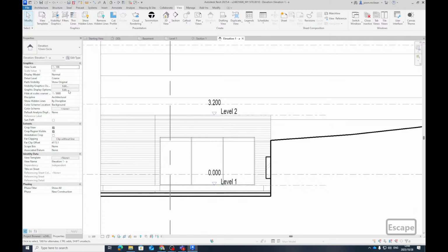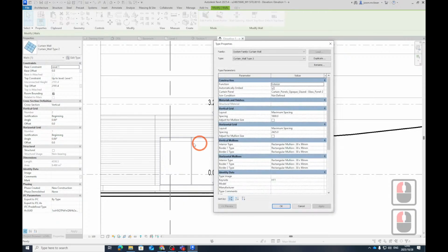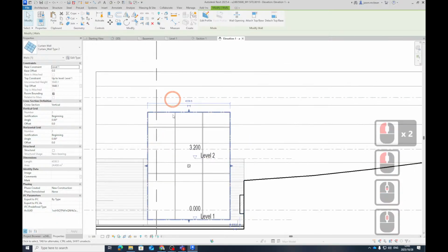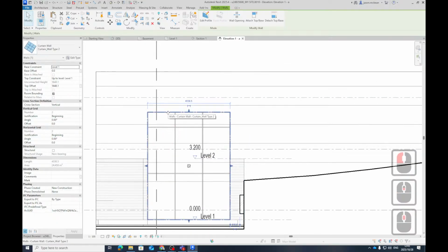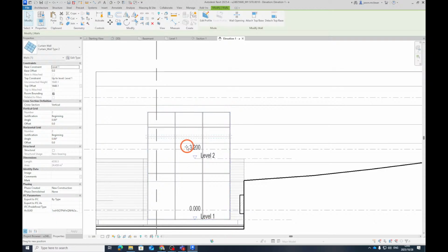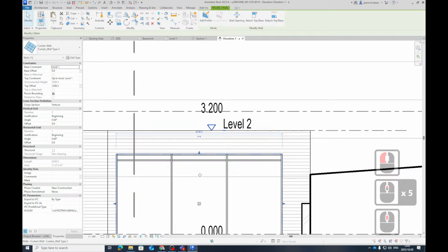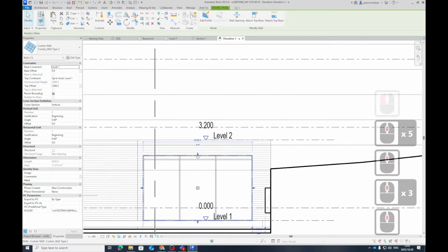Okay. So maybe what I should have done in this guy, this is tricky in the beginning. Okay. So I'll say fixed distance because I know those need to be fixed. So it means if I drag this up more, guess what? Every 400 it keeps adding that system. So these systems are strange, okay, but they take a bit of time to get your head around. You can't buy that glass any smaller, but if you go past it, it'll get rid of that system.